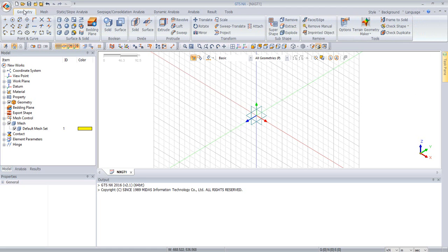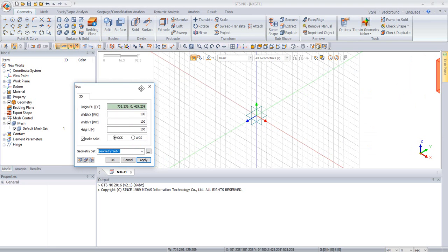So now we can go on to the geometry. There's different ways to do this. You can draw 2D and then extrude to make 3D, or you can also directly just create 3D objects. In this case, I'm going to create half the ground as a solid object, and then I'll extrude the pile itself. So you can see here I can drag this around and drop it anywhere I want, and there's coordinates telling me. Or I can directly just input these coordinates.